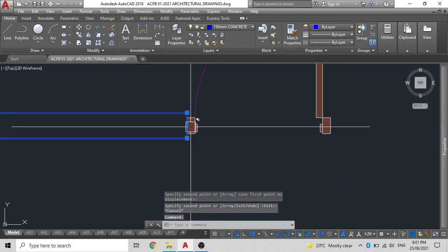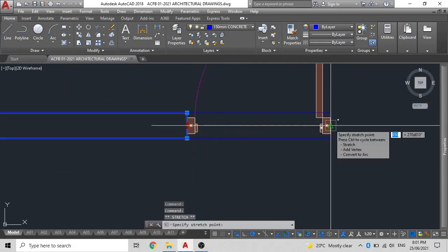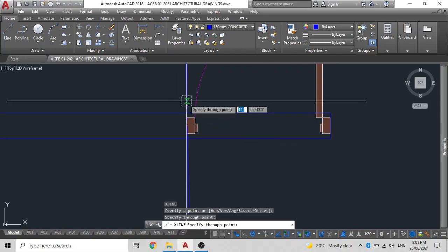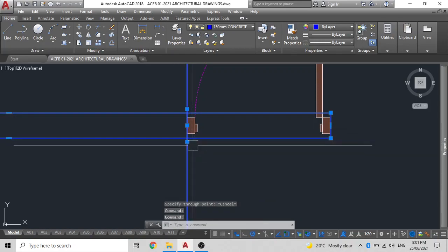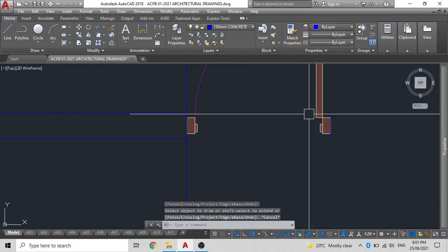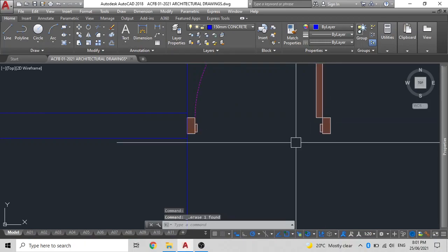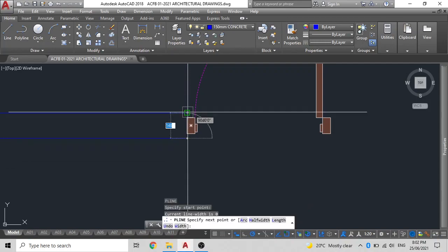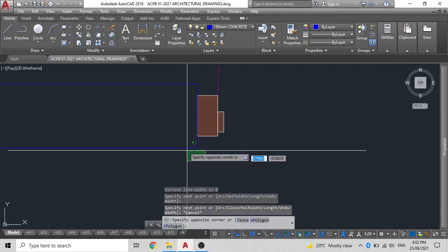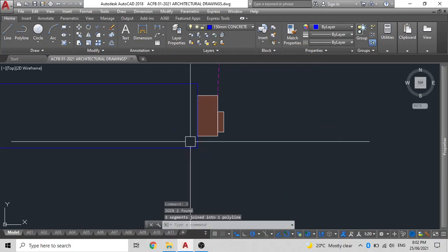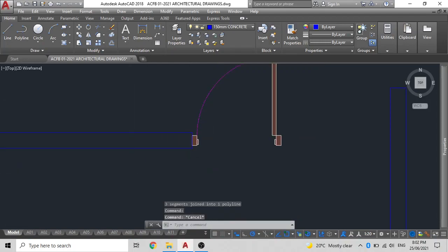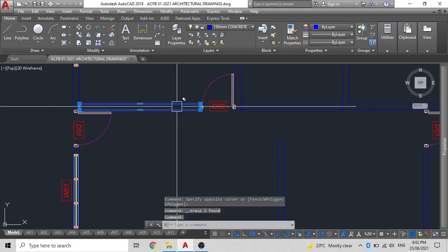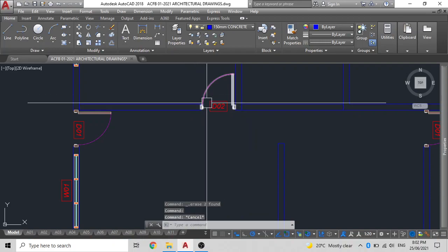It will be quite difficult. We'll use the same procedure. As you can see, now you have to delete quite a number of lines. Then you'll have to draw another line. Then you'll have to either 0 radius fillet or just join them. In this case, I'll join them, J for join. And that will waste at least a few seconds of your time. So multi-line style is actually better to use because it has the option to trim automatically.